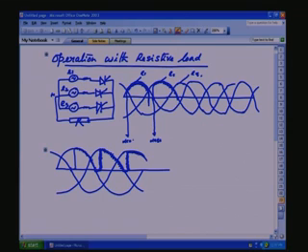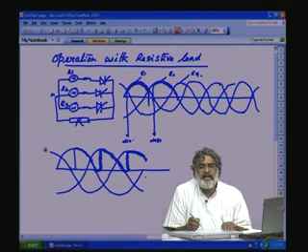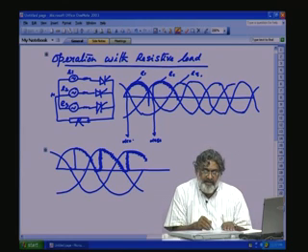What it shows, with the resistive load, there is a discontinuous conduction depending on the firing angle. That means alpha more than 30 degree, there is a discontinuous conduction. Now, as the alpha increases, the part of the input mains coming across the load will slowly get reduced.